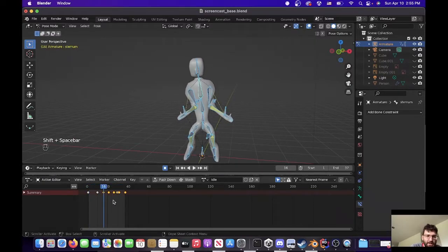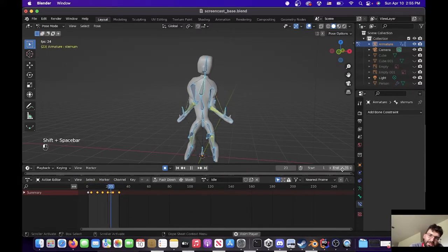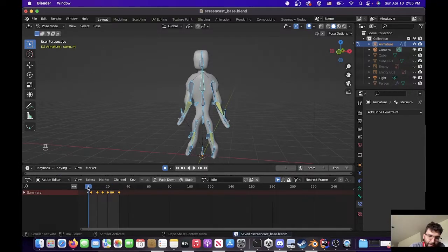And if you want it to really look like it's looping, the last thing you've got to do is drag this in, set the out point at 31 frames. And now he's like sort of dancing in place a little bit. We're going to call that his idle animation. But now we need one more because I promised you two. We're going to go to this button, new action, and we're going to call it run.